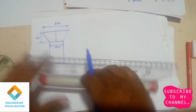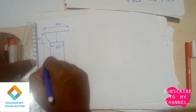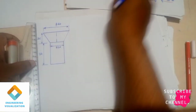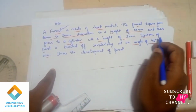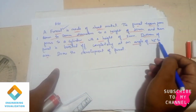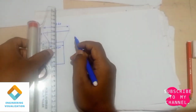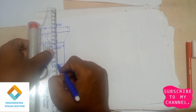Can show the dimension for it. It is 50 mm in length. Now we need to cut this lower part of the cylinder at an angle of 45 degrees. You can see the question. So the bottom of the funnel is beveled off completely at an angle of 45 degrees to the axis. Okay, that is from one end. So we need to draw an angle line, and that should be at an angle of 45 degrees.